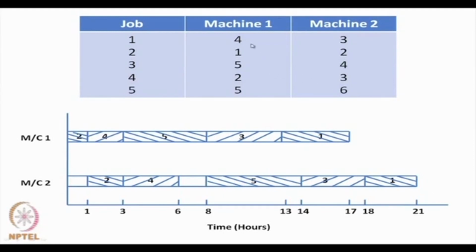Once that is assigned, we take away job 1. Now we are left with 3 and 5. The minimum is 4, that occurs for job 3. So, that should appear just before 1, and lastly 5 should appear just before 3. So, the sequence for machine 1 is therefore first 2, then 4 and then 5, 3 and 1.